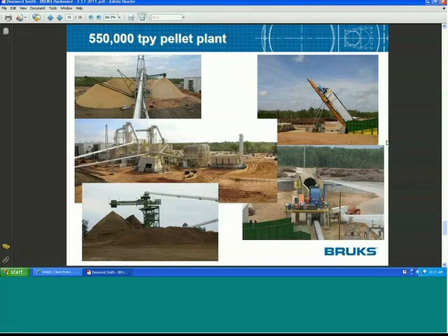This is a sort of a collage of photographs that show that installation. If you look at the center left picture, the A-frame building with the door off of it and the opening, that's the boiler feed bin. So the conveyor that is feeding it has that bark that's coming from the reclaim area. Anyway, the dryers are located just behind it. I don't think you can quite see them, but the rapid thermal oxidation unit is there to the right of that photograph that shows the gas treatment system that's necessary.